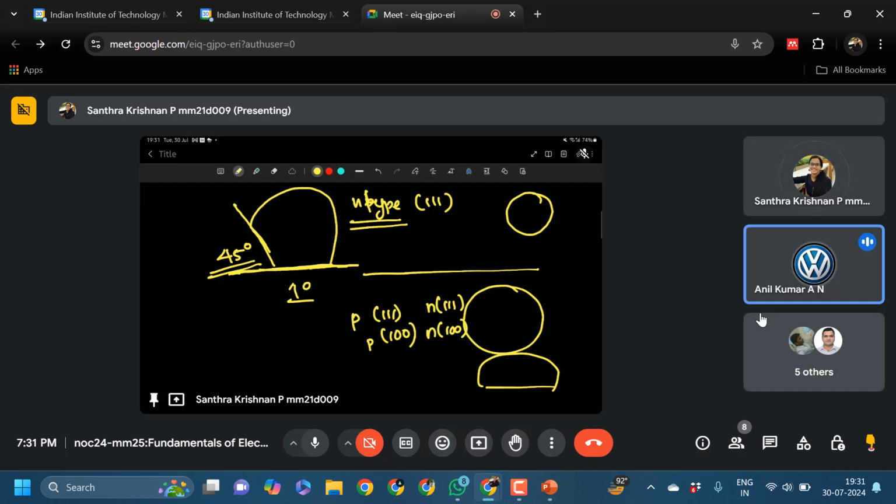If you give a wafer, you would have to measure its resistivity to identify whether it is N type or P type, and orientation would be very difficult to identify. If the manufacturer himself marks it and sends it, then it can be seen immediately and identified easily. Yeah, for that reason.